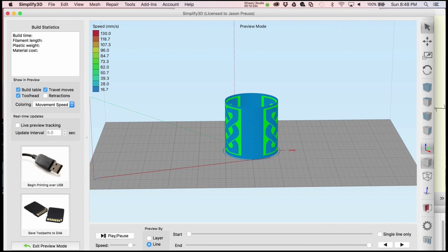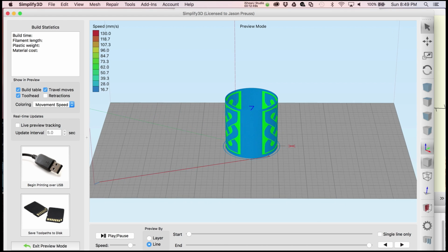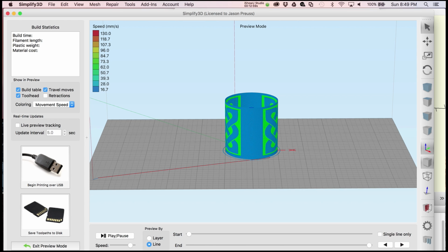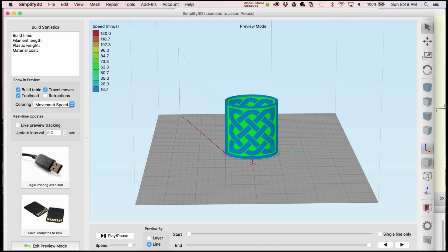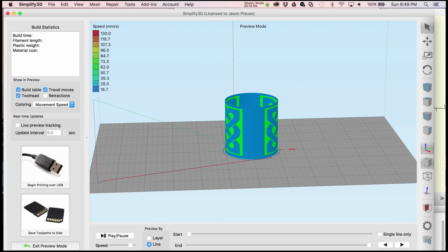In general, if you had a model, you could rotate the model and always use X, but there could be a use case for using Y, and in fact, I might use it myself. In Slicer I can set where the zipper is, where it changes to the next row, and you can set it in the back. So if you have a blemish in the print, you can set it where it isn't going to be seen, instead of having it in the middle here. But again, it's exactly the same as the X. You get the same warping on the edges when you're doing it on a curved surface.